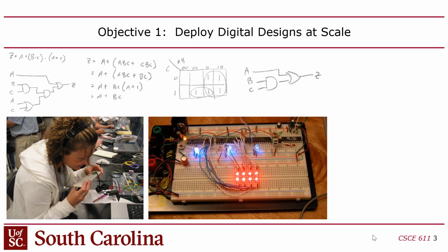And then you can take that digital logic and you can minimize it. You can convert it into a functionally equivalent but simpler form with fewer gates or fewer wires or less fan-in, using Karnaugh maps, for instance, or the Quine-McCluskey method. And then you could implement that equivalent circuit. And then hopefully you got some practice with breadboards, plugging the chips in the breadboards and the wires, and actually building the circuits that way. And that would be the physical implementation.